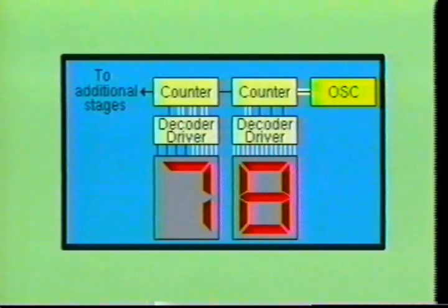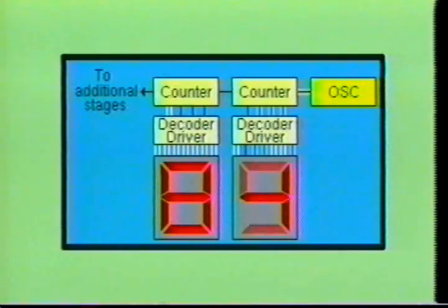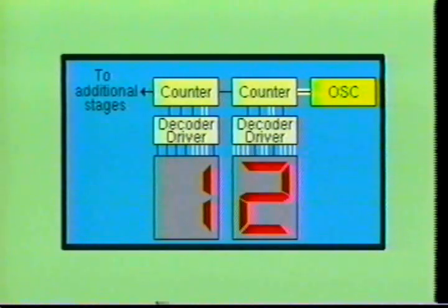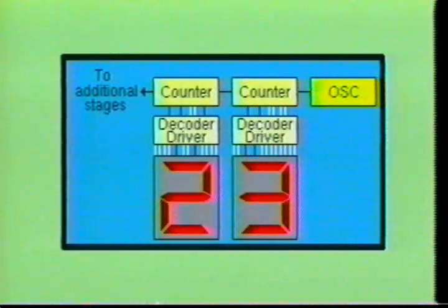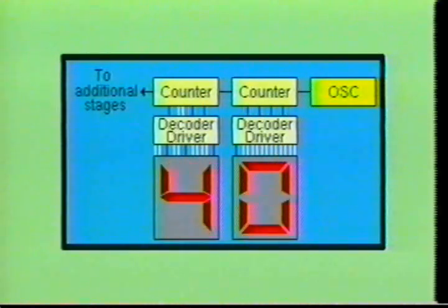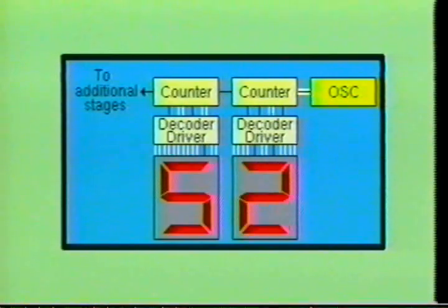a 7-segment display. When the first divide by 10 counter reaches 9, it resets back to 0 and outputs a pulse into the next divide by 10 counter. This pulse activates the second counter circuit and causes it to produce BCD coded outputs into its decoder driver circuit. The decoder driver IC causes the 7-segment display to show the divided down pulses in a numerical form. By simply adding more counter decoder driver 7-segment display devices, this circuit can be made to count to any desired length.